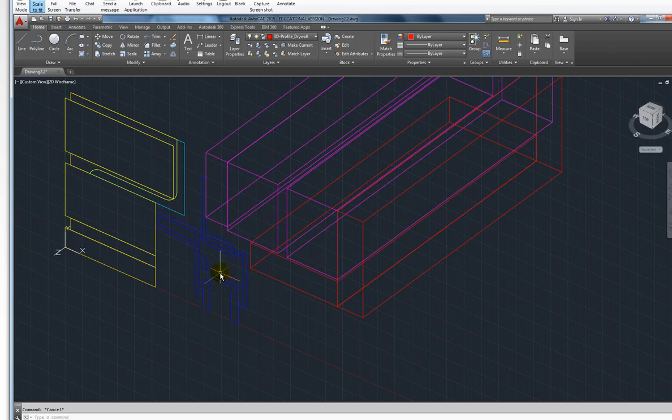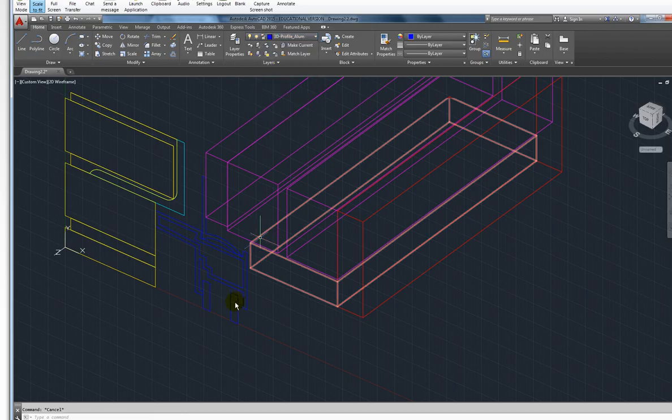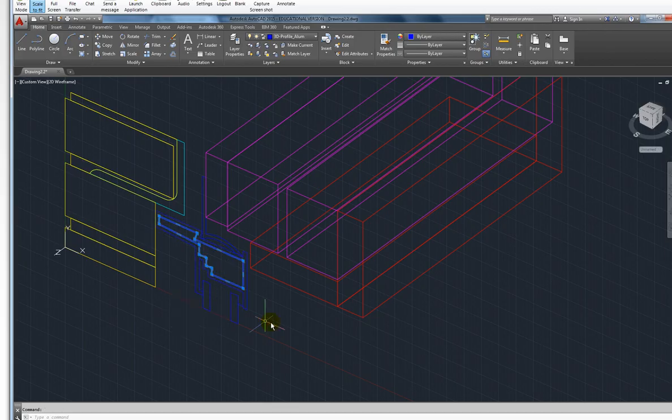Okay? So if you have two shapes sharing a line, you might run into problems. So don't produce double lines. Is that your question? Yeah, because I think I did that a lot in the drawing. Shared line, I was thinking. So there's a command called overkill. Overkill will kill all your double lines. But you need double lines. Yeah, you need to add those. So there'll be double lines. Yes. Because they're closed shapes.